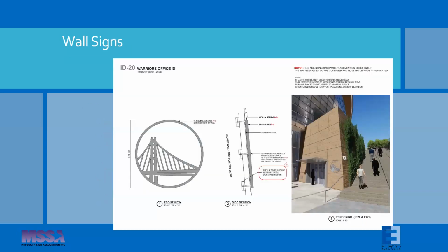So this is an example of a wall sign, and it's frankly about as simple as it gets. This is a flat cut shape, flush mounted, lightweight, and pretty simple. It's an open frame sign. It actually does pose a bit of a mounting challenge. So what was important in this case were two things. One, we needed to know from our client, what was the wall type? So the surface of the wall, and then what was behind the wall, so that we could specify the connections and if blocking was available to be installed or not. And so that determined the mounting method for the sign. Or, again, communicating with them, are there any mounting limitations that we need to know? Because there's several different directions that we could go.